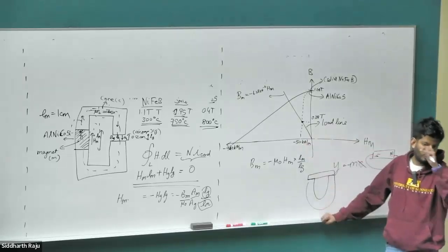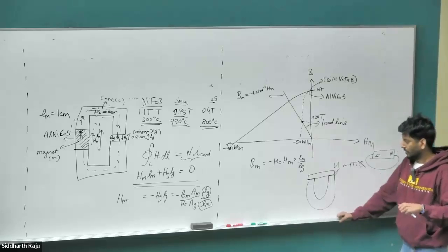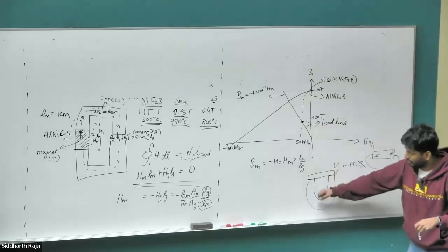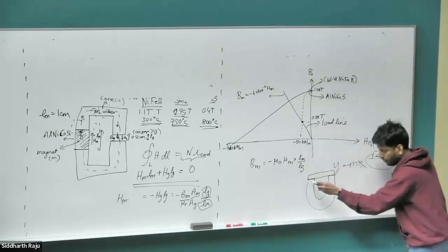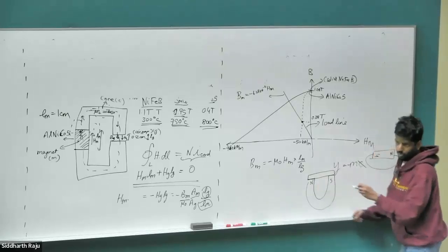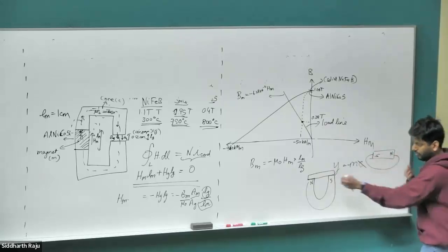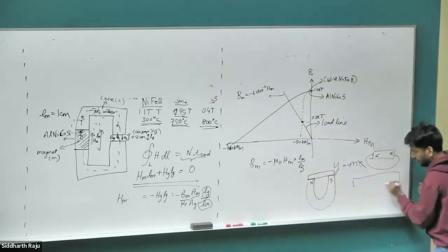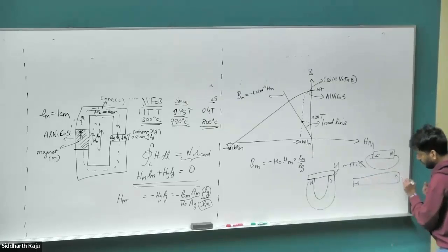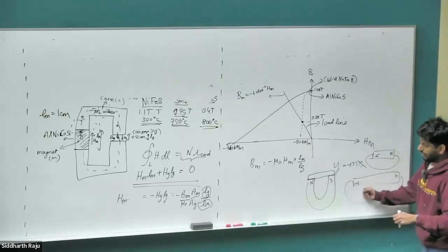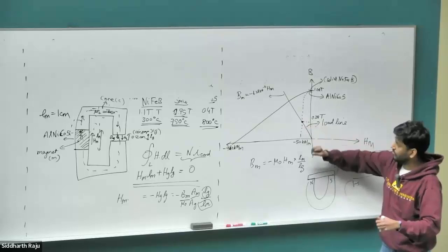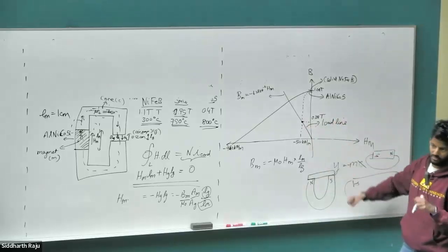That's it. There's no way to build the field back up again. So that's why, first of all, the Alnico magnets are shaped in this weird horseshoe structure so that the north and the south poles can remain as close as possible. Because if you have this bar-like structure, the length of the full magnet, so if you extended this into a full bar, it's going to be extremely large. So the pathway for the flux to close will be very large, so the air gap will lead to very low B field, which can then be quickly demagnetized by stray field.